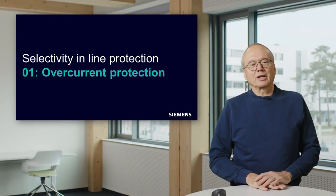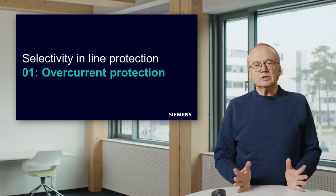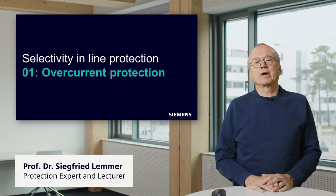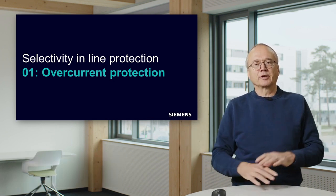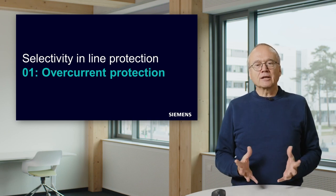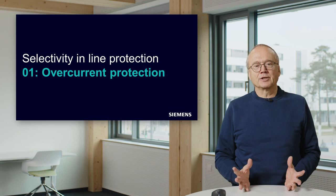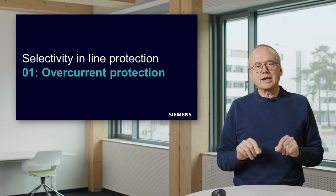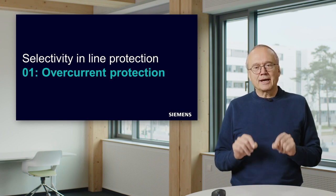In this video I would like to talk about selectivity in line protection. Remember, what is selectivity? If we have a short circuit somewhere in the network, the short circuit current is flowing through different ways to the short circuit location. That means in our network several relays will see the fault current, and selectivity means that only the relay of the affected line or transformer has to trip.